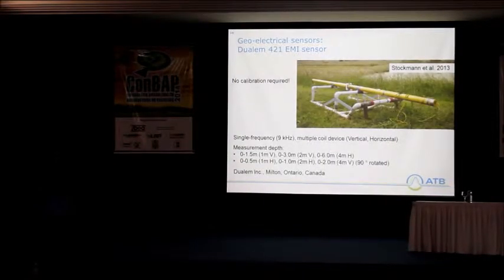Another manufacturer is ULM. The good thing about this sensor, it needs no calibration. It's very robust in that respect. It also offers a couple of spacings within this sensor, so you get readings from 3 depths.